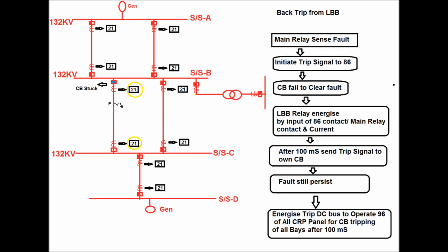But again, the circuit breaker fails to clear the fault due to breaker pole stuck or breaker pole jam. Therefore, the fault still persists.